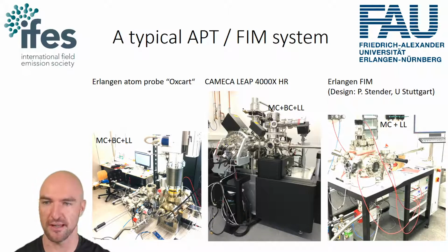We've got a lot of stainless steel being used here, simply because if we want to have that ultra high vacuum that we need for our atom probe measurement, we will need to heat up our system to an elevated temperature, above typically 100 degrees C, usually much higher, 150, 160 degrees C, while we're maintaining pumping, so that we can get rid of surface contaminants that are inevitable when you open the system.